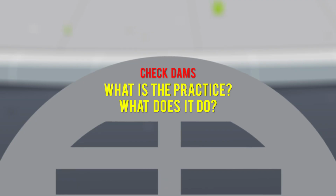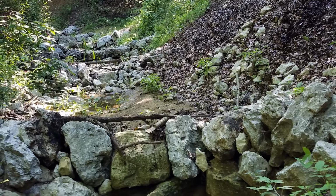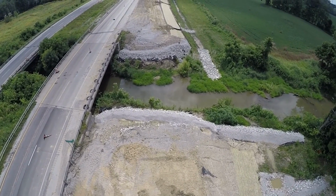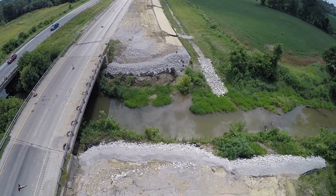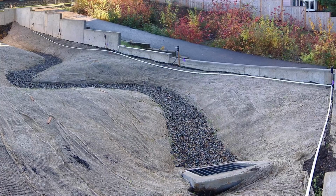Check dams. What is the practice and what does it do? A rock check dam is a series of runoff control structures consisting of geotextile fabric and aggregate placed across drainage channels to slow stormwater runoff. This measure may also provide limited effectiveness as a sediment control measure. How does it work? It reduces erosion and flow velocities in a drainage channel.